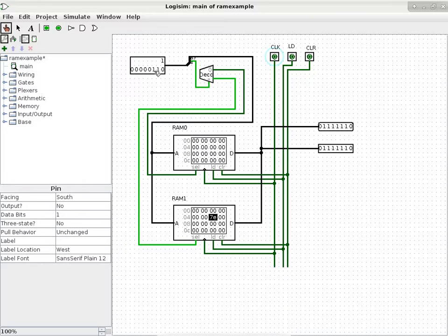There's a delay. So the numbers that we were looking at, each number is corresponding to one stage of what you need to do to work with a memory bus. Are we doing okay so far? And those are in nanoseconds. What about changing the load line? If this is originally a 1 and we turn it into a 0, it would take time for the RAM chip to respond and go, oh, you want a write operation. I'm going to switch gear and prepare for a write operation.